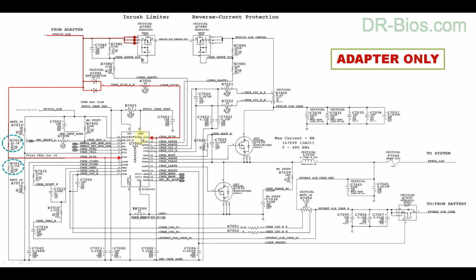So the adapter voltage has entered the IC, and in the next step, after providing PP3V42_G3H voltage, an SMC_reset_L signal will be generated that will be analyzed in the next video. And as you see, these two enter these pins of the IC.